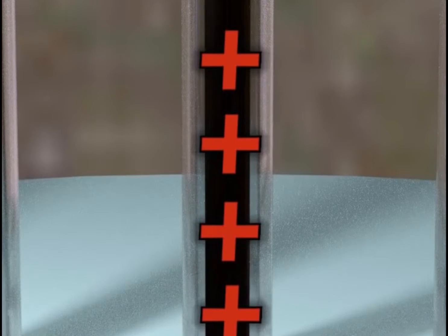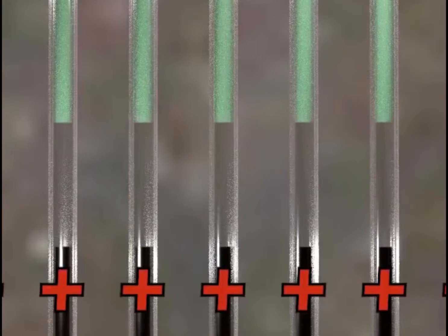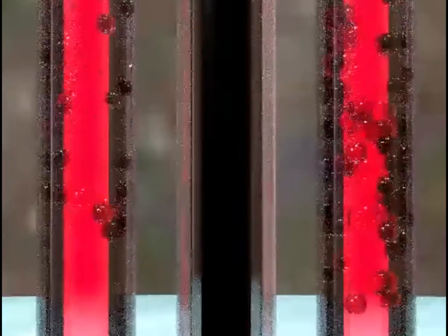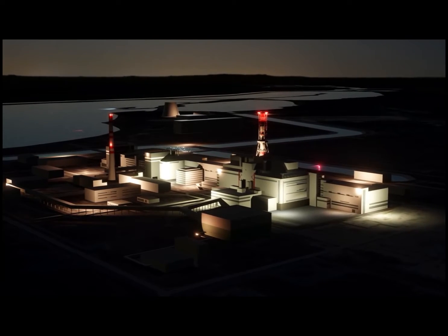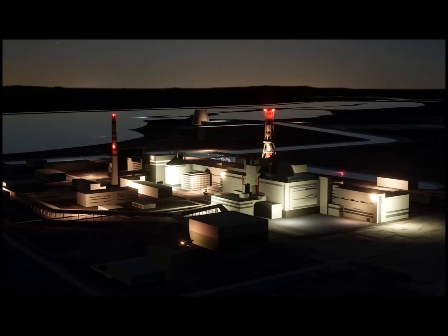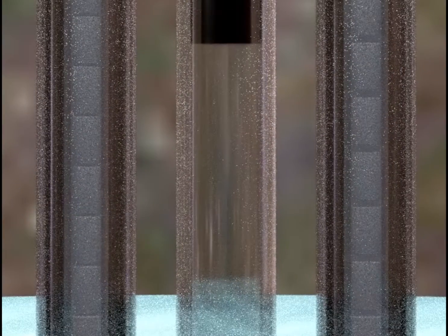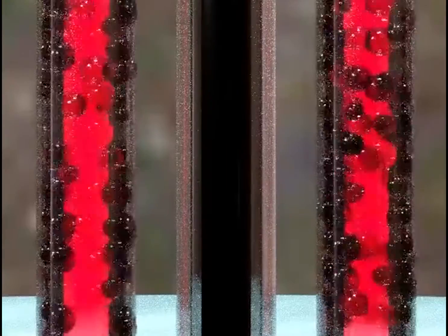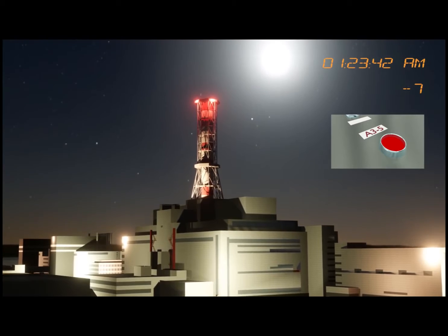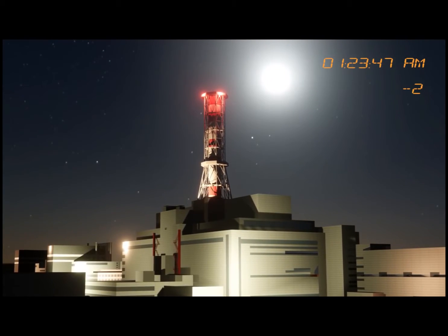Remember the diagram of the reactor I showed you earlier? Let's consider that by any chance there is a surge of power, and there is a very good possibility that steam is generated inside the core of the reactor just next to the fuel rods as voids, and the steam is not really as good as water in absorbing neutrons and cooling. As a result, the neutrons get well exposed to the other fuel rods, increasing the reactivity enormously, which then again creates more voids, more heat, more neutrons, more voids, forming a chain that increases the reactivity to an enormous amount, unchecked. It creates a positive feedback loop that just throws everything out of control.